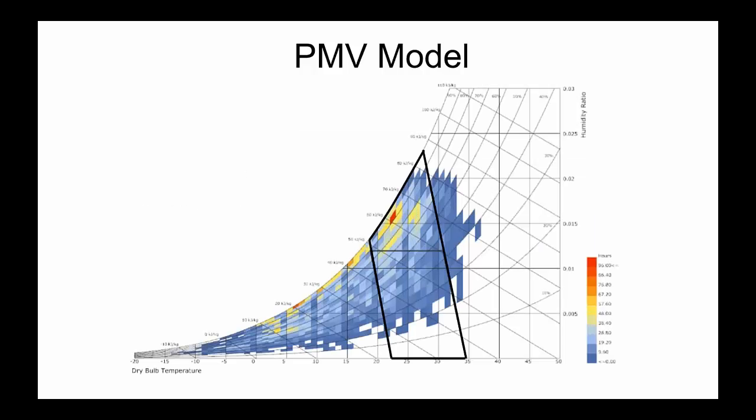And it's still very common practice today that people will try and visualize PMV comfort by plotting results on a psychrometric chart like what you see here, where you essentially have dry bulb temperature on the x-axis, absolute humidity on the y-axis, and then you essentially will use the PMV model to plot out the region that is comfortable on this chart. Basically, although this polygon moves around a lot based on all those 6 factors, not just air temperature and humidity.